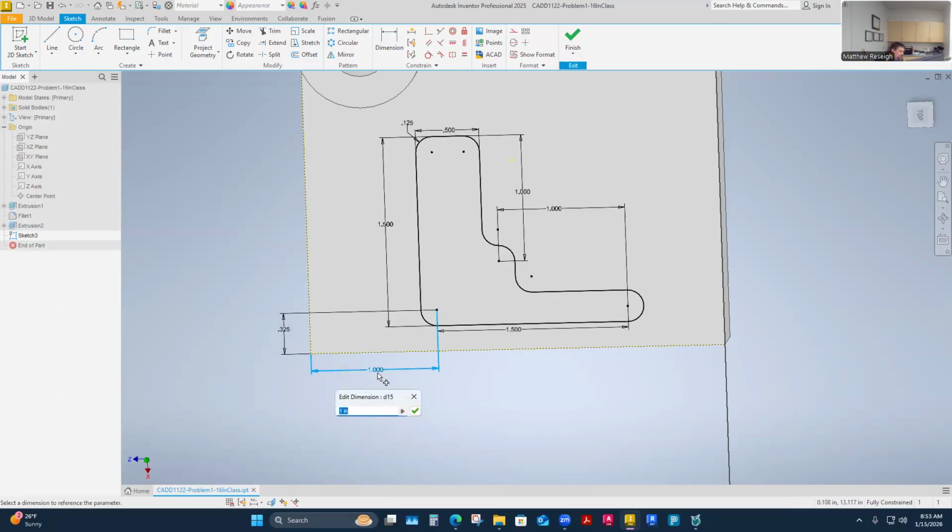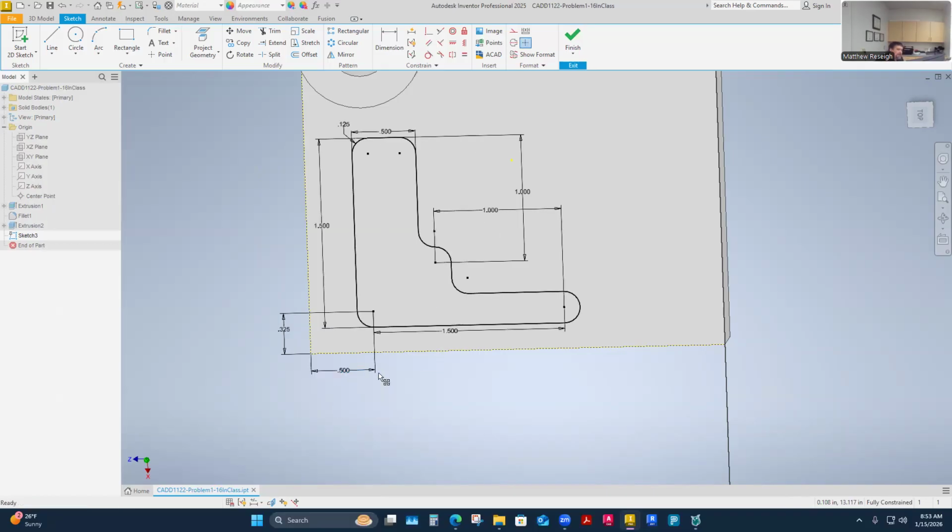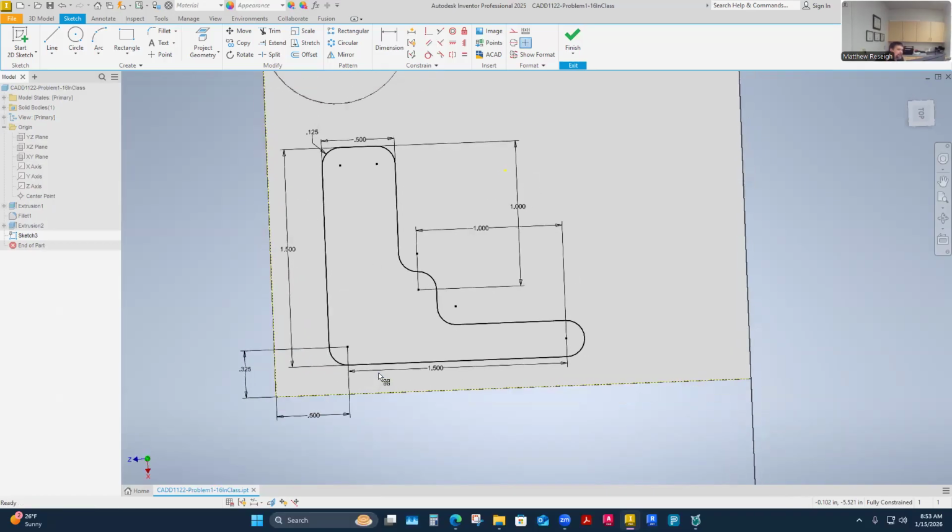And that's called flexing. We don't have to do that yet, but we will start flexing. If I really want to make sure my sketch is robust and moves how I want it to move, I can start changing some of these dimensions. Everything should stay constrained, and I should get the geometry to move how I'm expecting it to move.